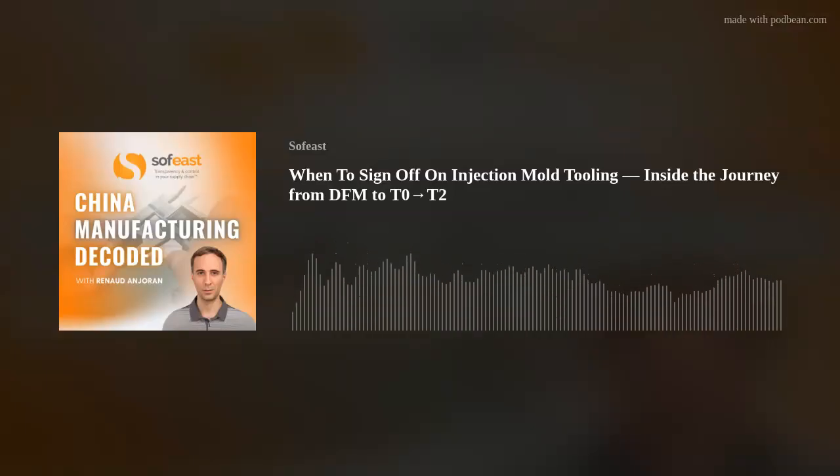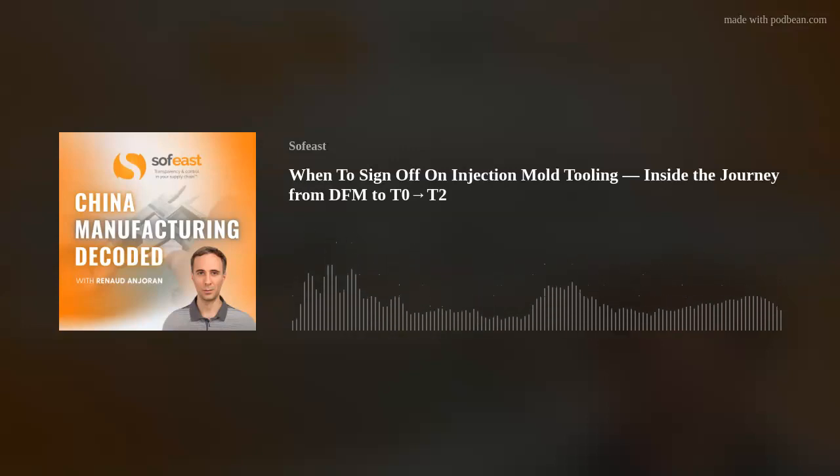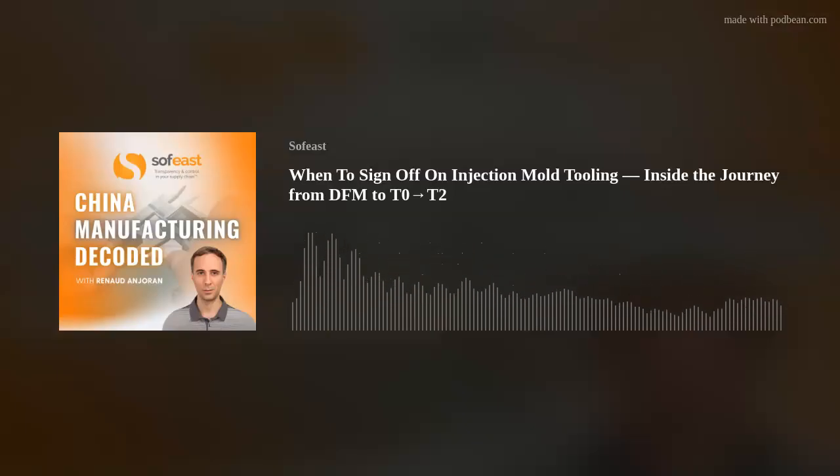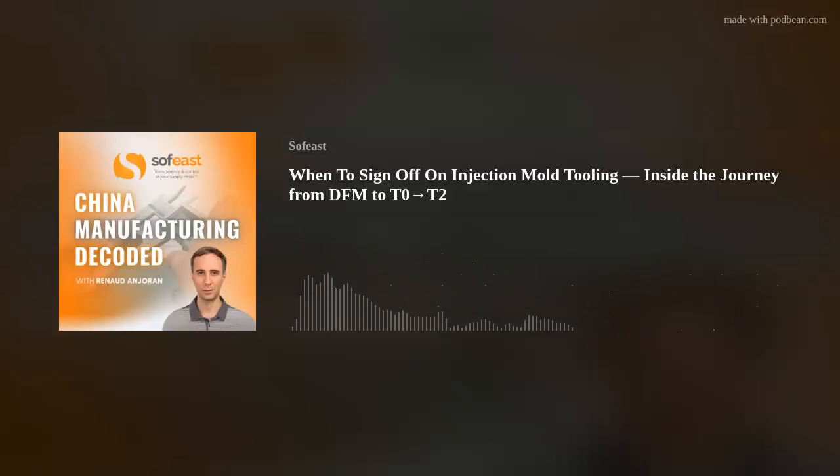We then start to introduce some polymer. At this stage, it could be the material or polymer intended for production, but it could include a load of regrinds and stuff like this. We don't really want to be running virgin polymer through just to try this, so we generally run a lot of regrinds and reusable or recycled polymer.